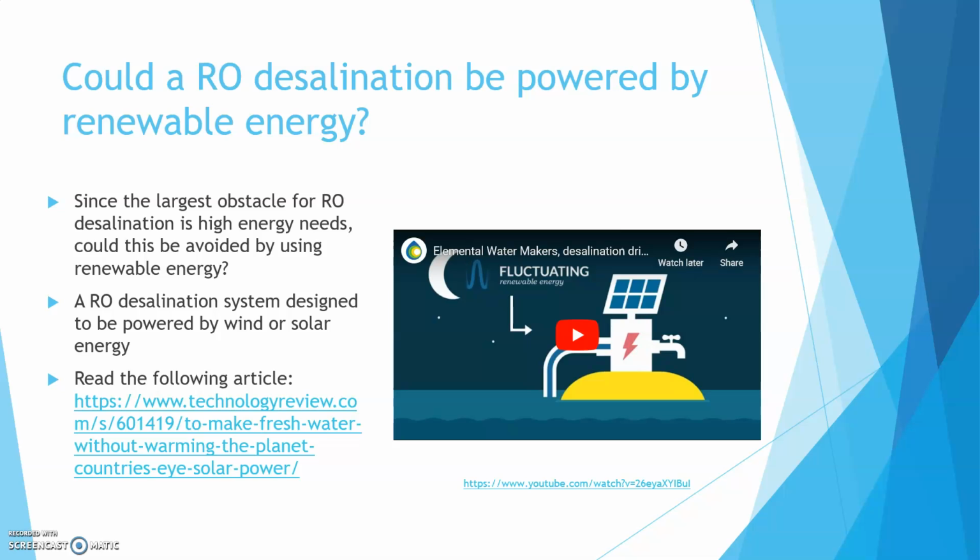And what is the other related information we should know before doing the desalination process? As we stated earlier, we should understand the difference between passes and stages in reverse osmosis, and single pass and double pass reverse osmosis, which depend upon the nature of the water to be purified and the nature of contaminants. Normally, what type of contaminants can be eliminated through the reverse osmosis process?